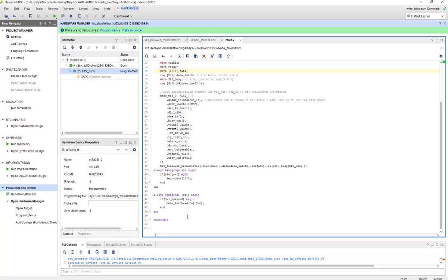So I was thinking, hey, the SPI on both sides are talking through the same signal. So I was using the 100 megahertz to update all the data lines. I was worrying about the speed mismatch. Because the 100 megahertz as a clock for the XADC is just running inside the XADC. It's working on doing conversions, and it's just making the data available at the output, right? It doesn't matter what else is interfacing with it, because the clock is just being used for the XADC, all right? So it's just making the data available at the output.